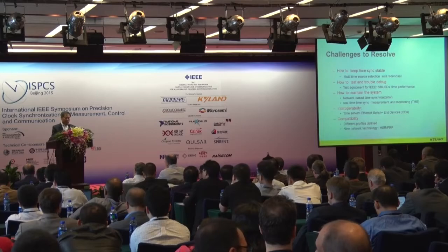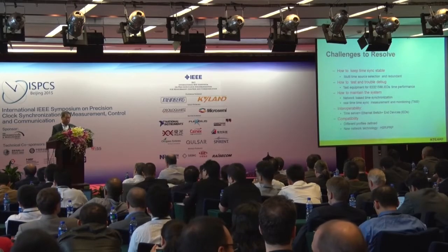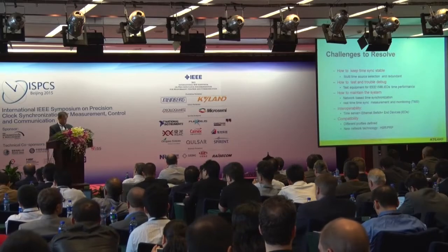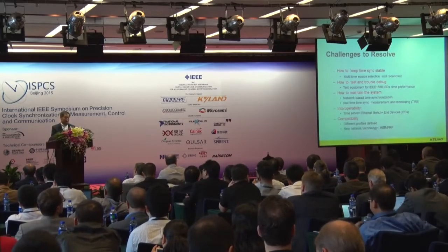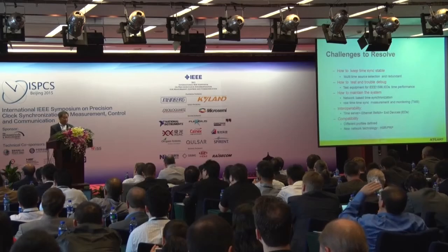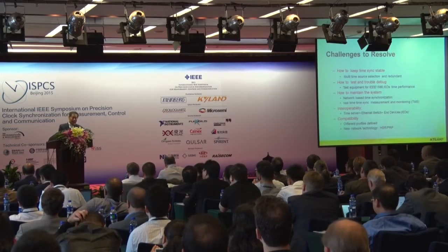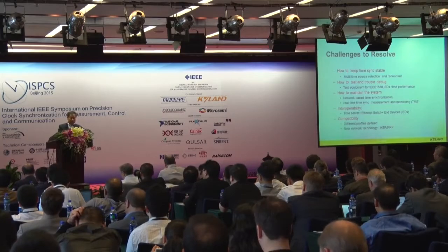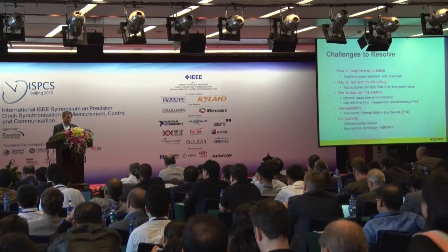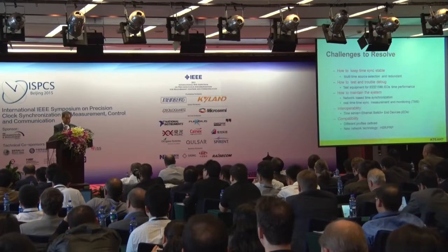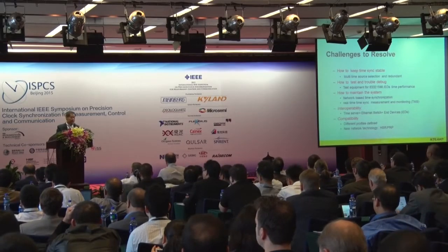This is more work in the substation. Also, in the substation we have to monitor the time difference in real time. If some merging units lose time synchronization, there may be big trouble, so we monitor the time synchronization performance in real time. We call it TMS.